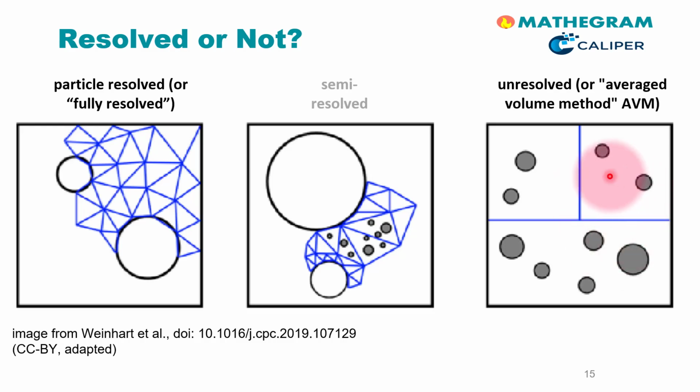This requires closures for the fluid-particle interaction forces, for example the drag force, which are necessary to make reasonable predictions. The CFD results, specifically the pressure and velocity, are an input to these closures and are not directly used to evaluate fluid-particle interaction forces as in the resolved approach.